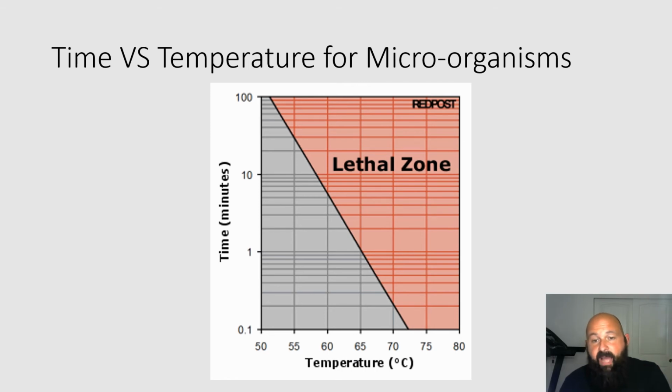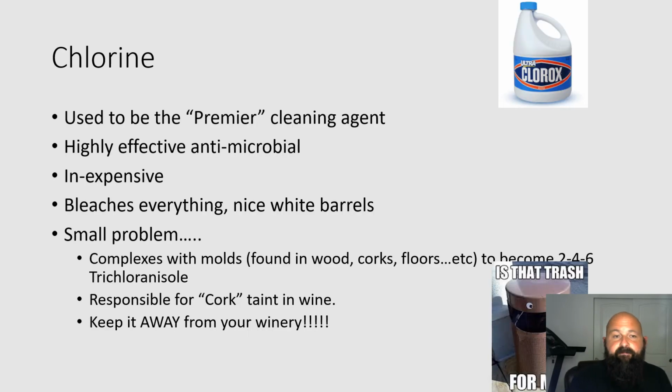But this is that lethal zone, and it gives you an idea of how quick your time versus temperature needs to be in order to get that tank sanitized, and pretty much free of most microorganisms. You can't get rid of all of them, but you get rid of 99+% of them in a pretty short period of time with some heat.